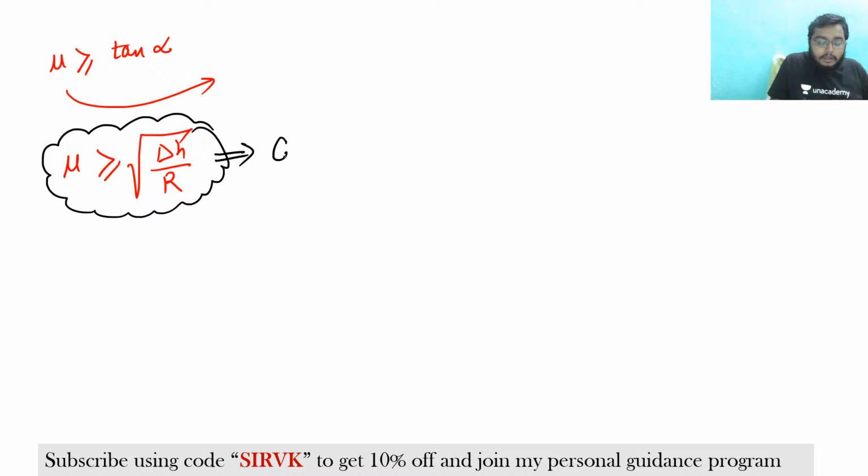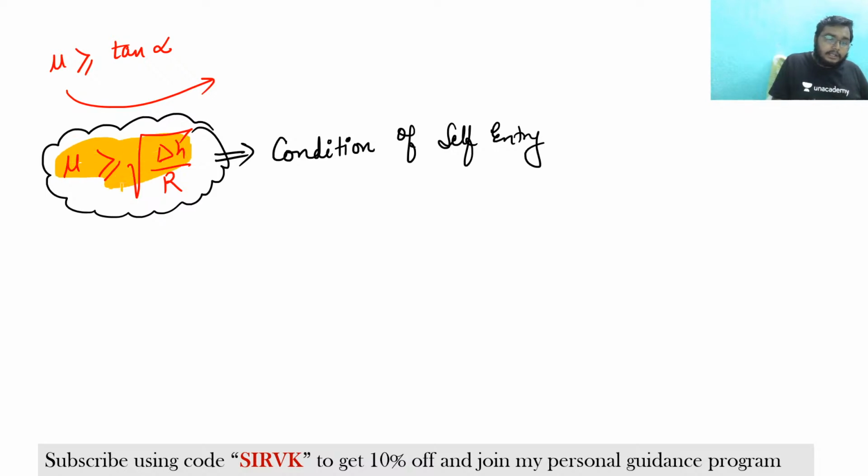So remember, the condition of self entry is this: mu is greater than or equal to root over delta h by r, where delta h is the draft and r is the radius of the roller. Fine. Okay, so this is the condition of self entry.